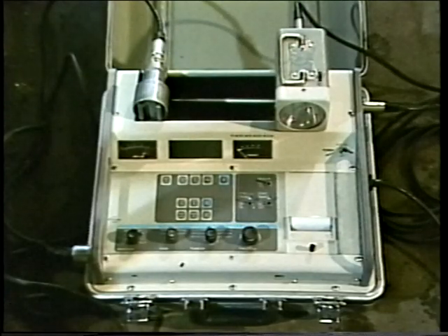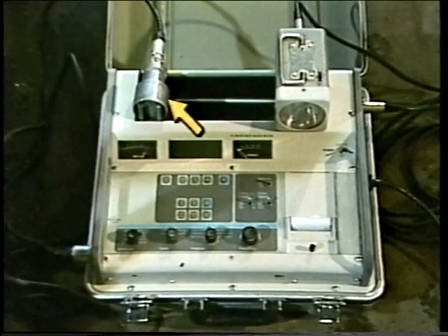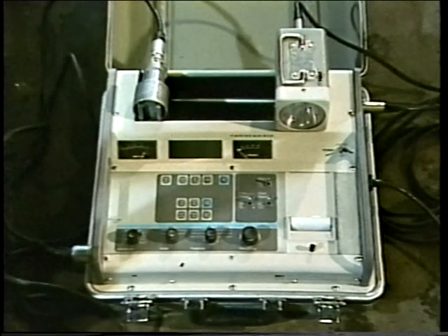Vibration analyzers are available in two basic styles: self-contained units and units that use a computer to analyze the data. There are many variations of these two styles, so the ones that you see here may not be identical to the ones that you'll use. However, they all perform the same basic functions. Here's the analyzer that we'll be using. It's a typical self-contained model consisting of an instrument and a pickup, which is connected to the instrument. The unit is portable and can be powered by batteries or an AC outlet.